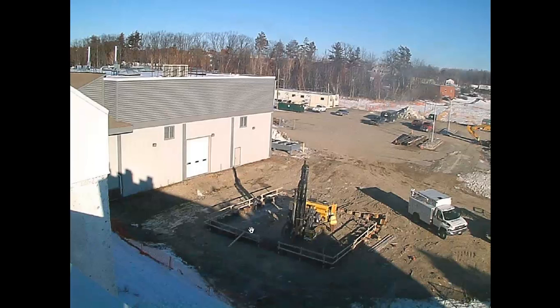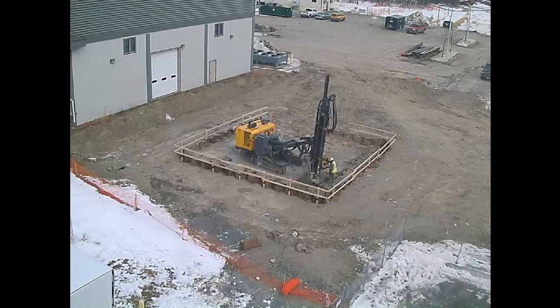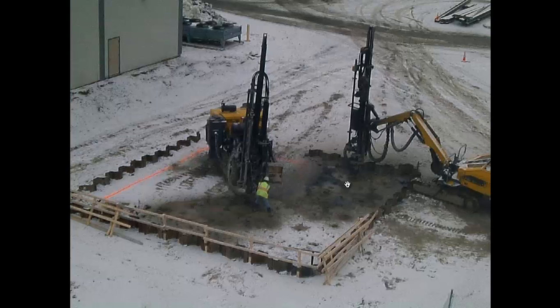We're going to drill these down to determine what the excavation depth is, and we're going to drill a whole series of holes. It was kind of interesting when they were doing this, because as they got more and more holes drilled, we could see, once they drill in one, you'd see water squirting up out of another one, so it was kind of cool. You can see this pattern of holes that they're drilling to get a good profile of what the bedrock was underneath. Now, why was that necessary?